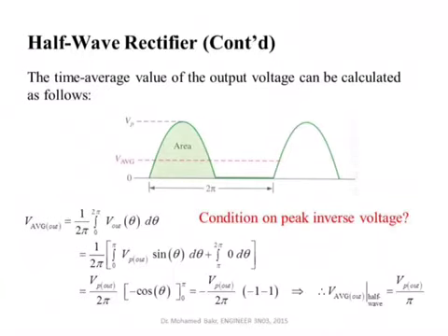So as we explained, a single diode rectifier will create an output waveform which looks something like this. It allows the positive part to go through, and it will completely block the negative part. Only the positive half of the cycle will go through. The negative half is completely clipped, and this is how the output looks. The peak voltage is not exactly the one that was applied to the circuit because the diode will deduct a little bit from that. So this is the original peak minus 0.7.